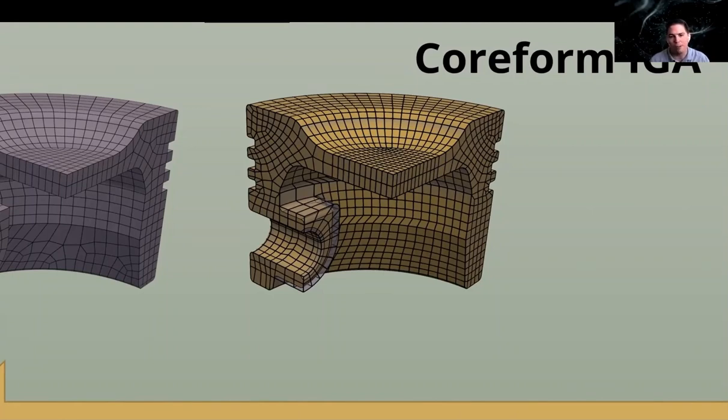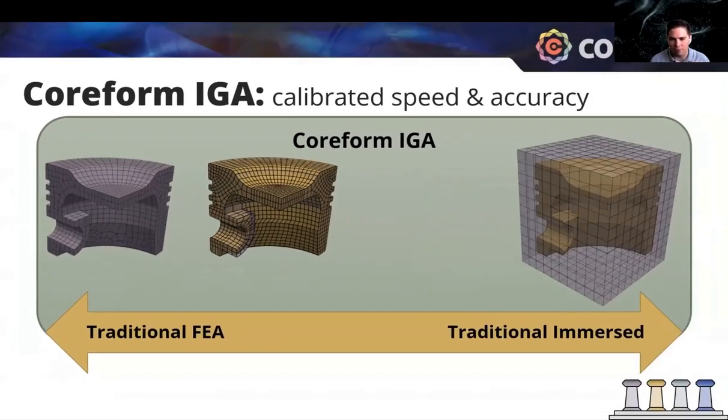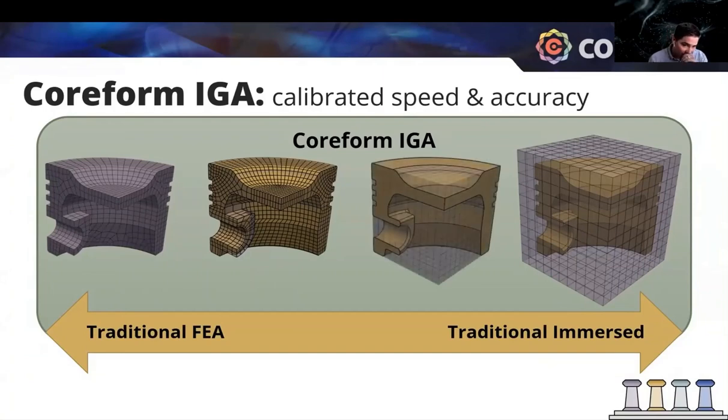We still get all the power of accuracy per degree of freedom by having body-fitted meshes elsewhere, but then the ease of being able to build a mesh by relaxing those tough constraints. Additionally, you can even go further and say maybe you only want to fit the major features of the geometry. So in this case, this quarter piston is effectively a quarter cylinder, and so we can immerse it in a quarter cylinder geometry.